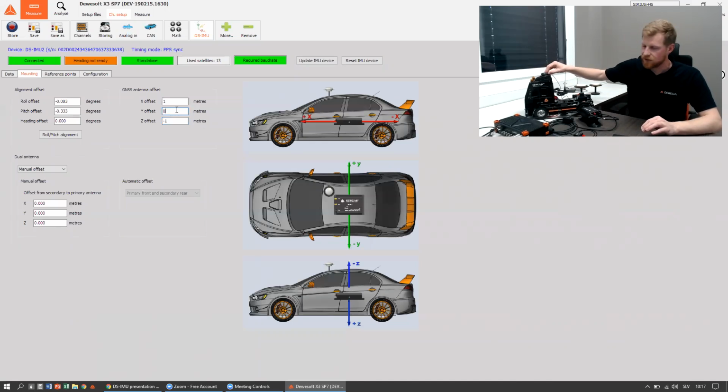And the antenna should always be mounted so that it is at the highest possible point. If that's a vehicle or a truck, it should always be mounted on the roof, and on the truck, the antenna should never be mounted behind a high wall, because otherwise we'll get really bad reflection or even multipath error from jumping of the signal or from reflection of the signal.